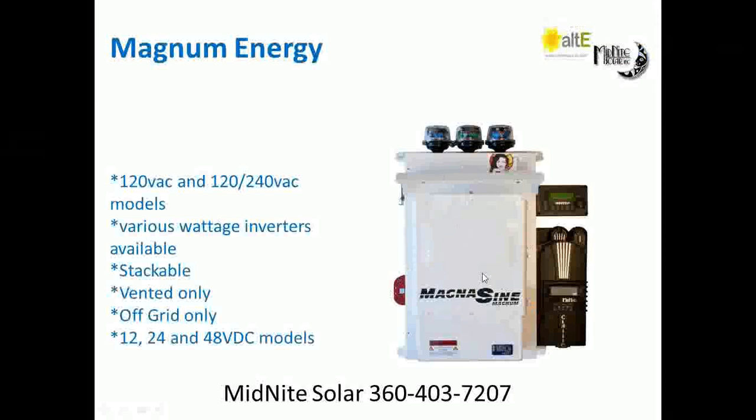If you're in an area where there's a lot of salt water, a corrosive environment, you may want to look at something like the Outback FX series that's sealed. And again, off-grid only. For the classification of this slideshow, we will call this off-grid only. It can grid interact, but it cannot sell. I do have a question.